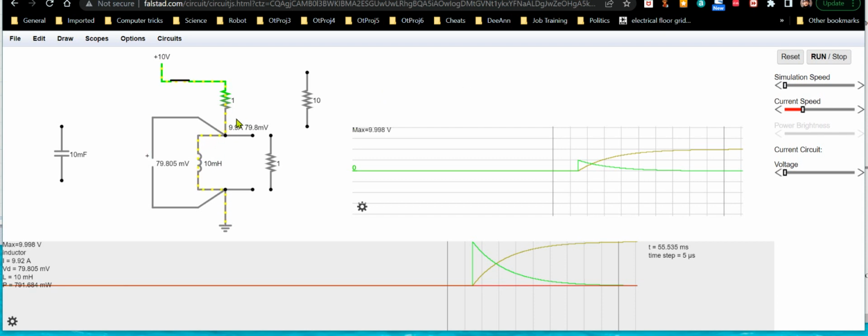It'd be like 1/100th the energy that it's storing right now. Because of that, it's a lot faster because it's having to store less energy in its field. So that's why it's faster with a bigger resistor, but with a smaller resistor, it's slower. In fact, if you remove this resistor, it'll have a certain natural charge rate to it.